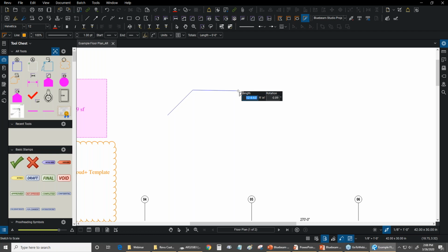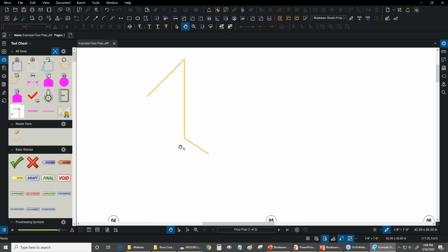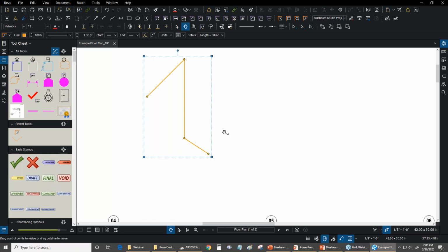So now let's do a negative rotation. We're actually going to move our mouse down here, and we can specify our length. Let's go 15 feet, tab, let's go to -90. So that's basically how you can go straight down. And we can continue this on, and that's it. Now, let's click enter again, and you'll notice that wherever my mouse was, it actually makes a new segment. So this could be a little bit counterintuitive at first.